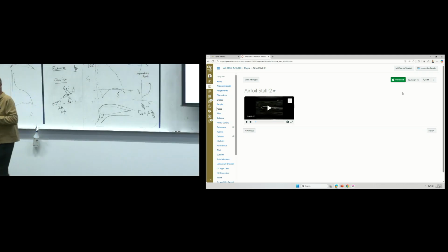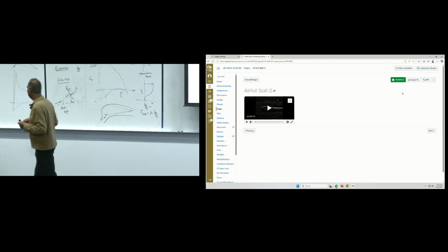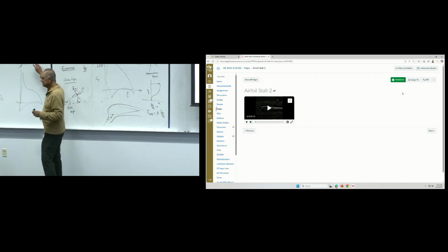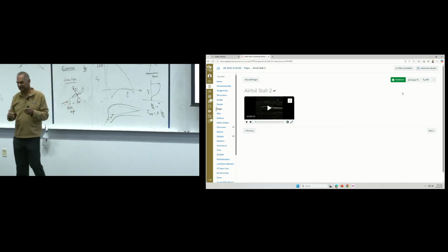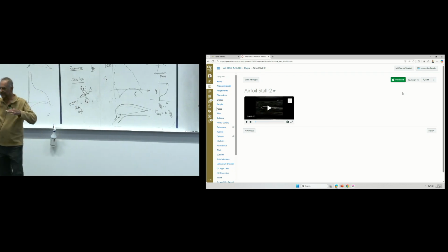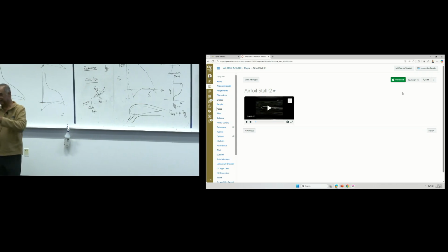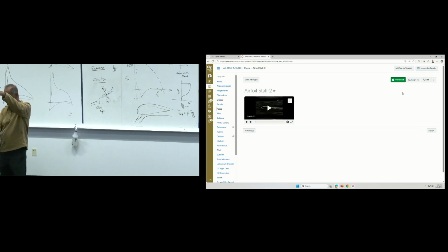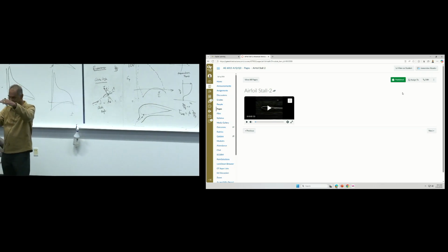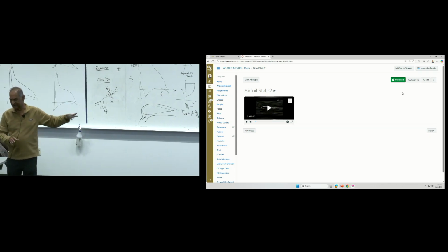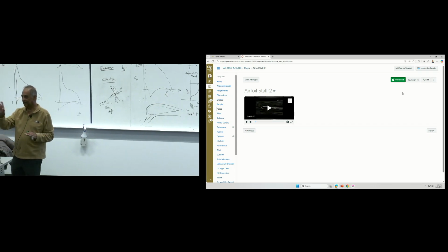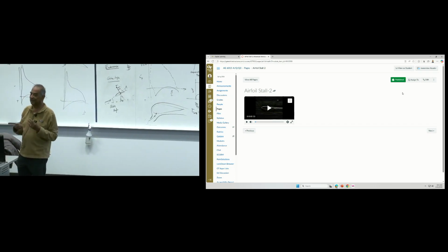Any questions so far? Yes, please. In leading edge stall, do we still have laminar flow after the leading edge stall, or just most likely it'll be turbulent? Okay, it'll be a highly unsteady, turbulent flow. Okay, the flow is so reversed. It's at that inflection point, and there's also more region for the eddies to form and so forth. So like that video we saw, at high angles of attack the flow is highly unsteady and turbulent.